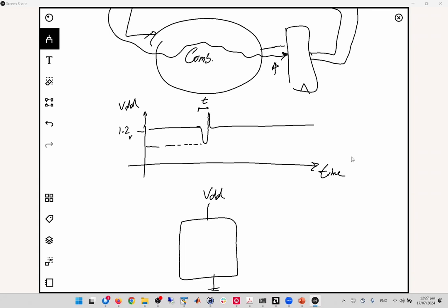It will completely burn. If you decrease it, again, there is a limit. If it's below, for example, 0.7, then no guarantee that it works. But at 0.7, it still works. If you bring it down to 0.7, the gates become slow, and you don't need to change the clock, or you don't have access to the clock, which stays valid as it is. But in one particular cycle, you make the combinational circuit slow in a way that, again, the output is not ready to be saved in the register.